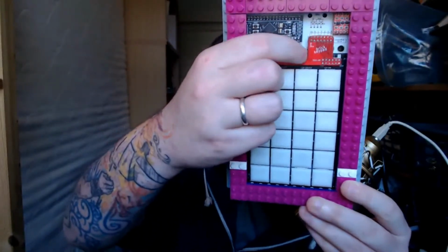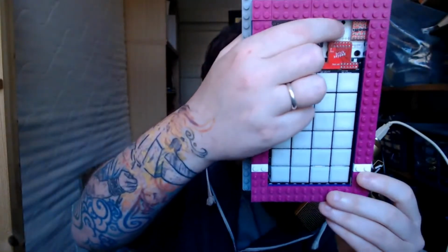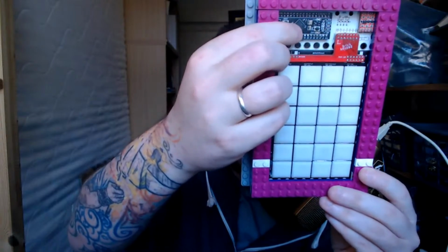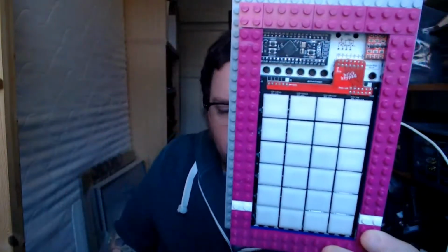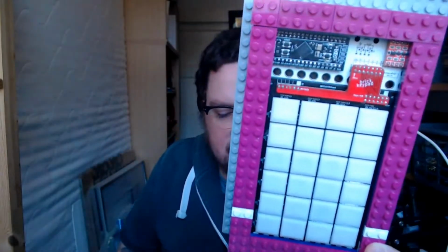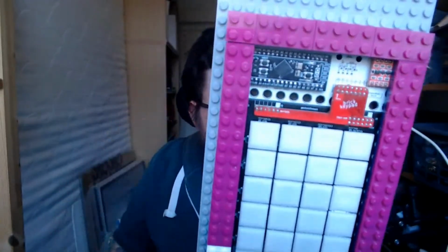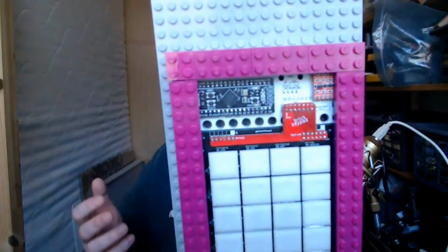And then I just do all the control. I made a little circuit board because I didn't want to do hand wiring. And I have another very simple board up here that just has a breakout for an off-the-shelf microcontroller development board. This is the WeAct Black Pill, so it's an STM32F411. So it's a 96 megahertz 32-bit processor that can do USB.